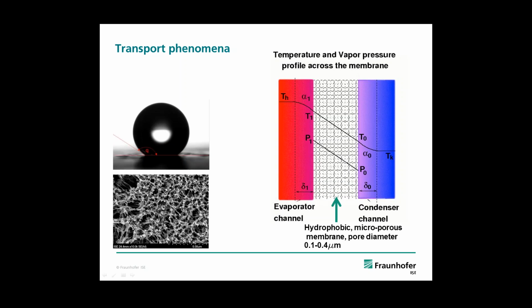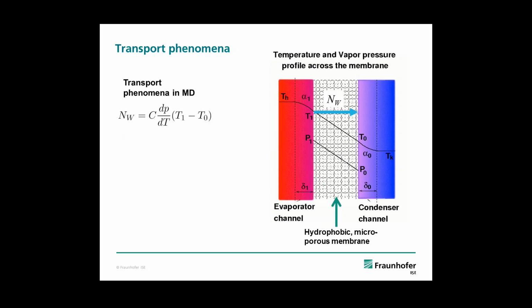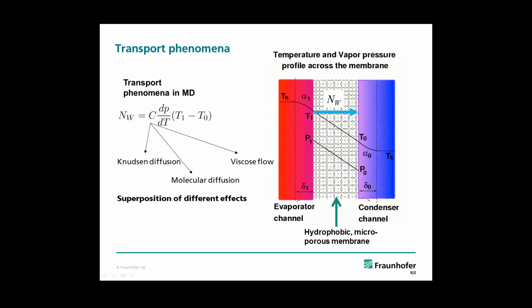He also asks, were there well logs that you could go off of? Well logs. Talking about the water quality. Yeah, there are two main sources in these technologies. We have seawater. The source is the sea, but it's not so easy to get the intake from the sea. So in most of the installations we drill beach wells to extract the seawater, and for brackish water desalination plants we take existing wells.